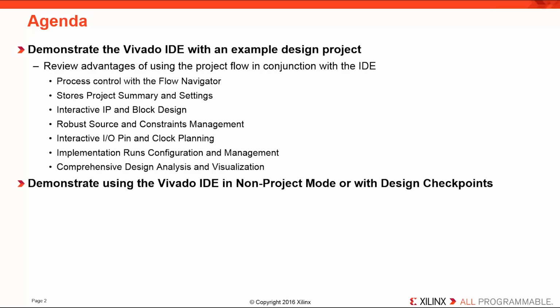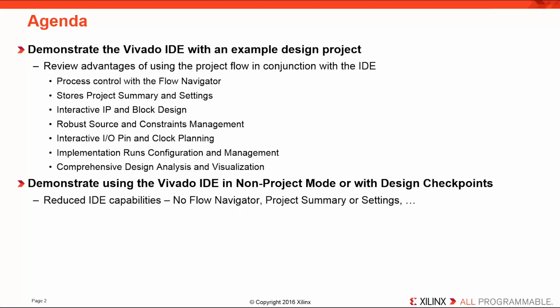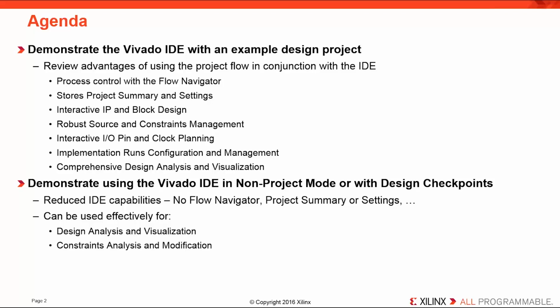The Vivado IDE can also be used in non-project mode or by opening design checkpoints. There is a reduced set of IDE capabilities. There's no Flow Navigator or project summary, settings, etc. But the environment can be used very effectively for design analysis and visualization at various points in the design flow, including after implementation, constraints analysis and modification. You can write out constraints into a new constraint file for the next time you run through the flow.